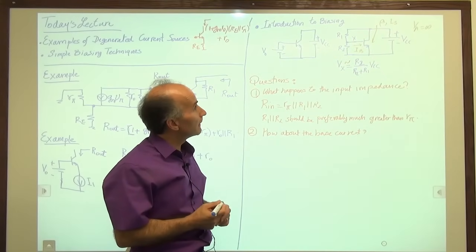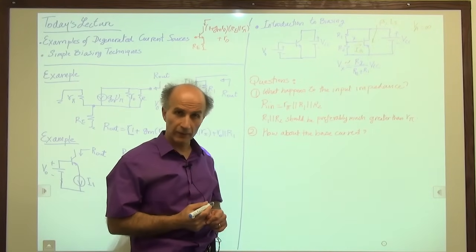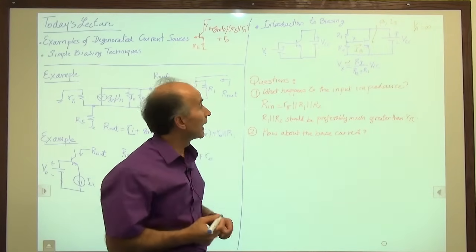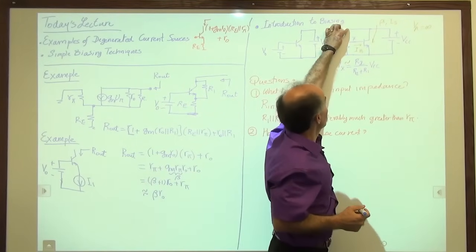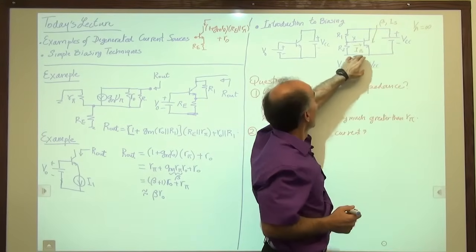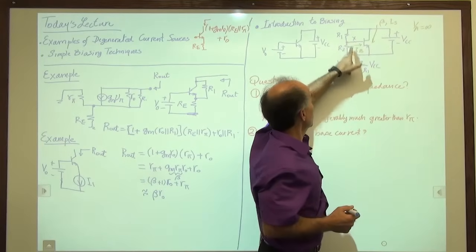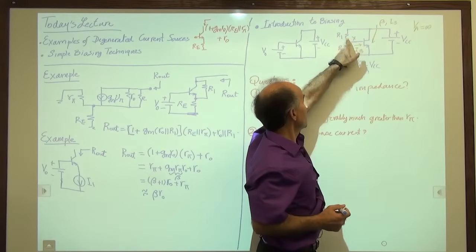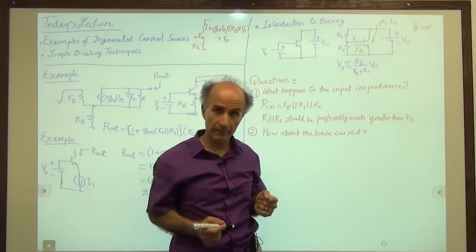All right. Well, I will play a little trick here to simplify the calculation a little. That's based on recognizing that this voltage comes from a battery, this battery here. So I can take this voltage source that goes to these 2 points, and this resistor, and construct a Thevenin equivalent for them.